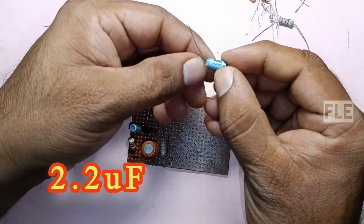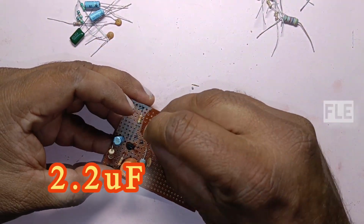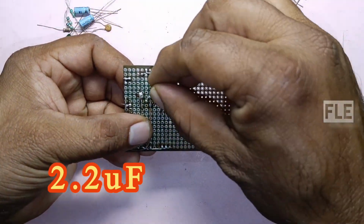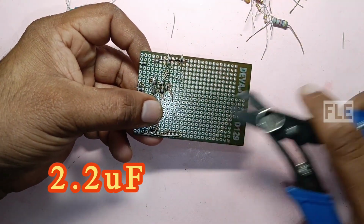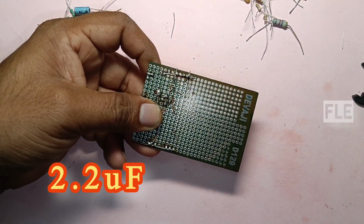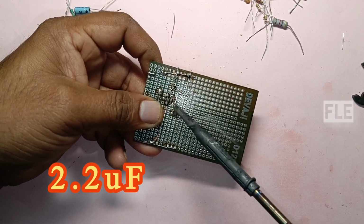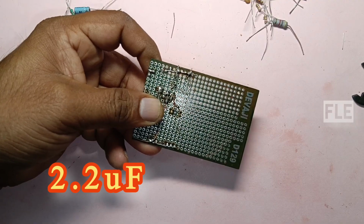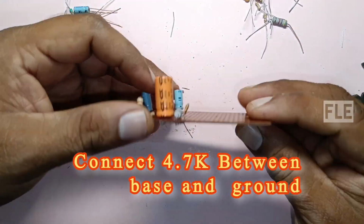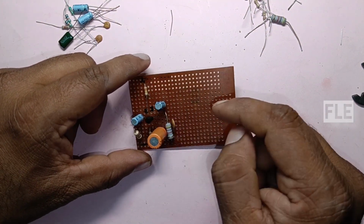The 2.2 microfarad positive terminal is connected to the emitter terminal of the C1815 transistor. Refer to the circuit diagram. According to the circuit diagram, the 2.2 microfarad positive terminal is connected to the emitter terminal of the C1815 transistor. Connect a 4.7K resistor between the emitter and the ground terminal.